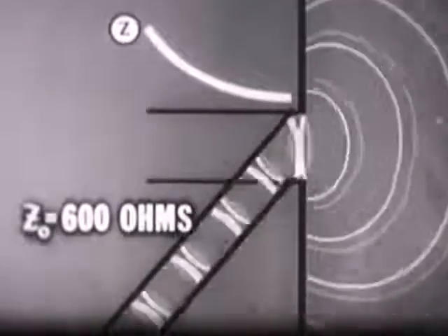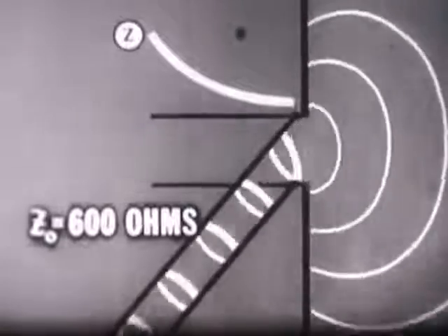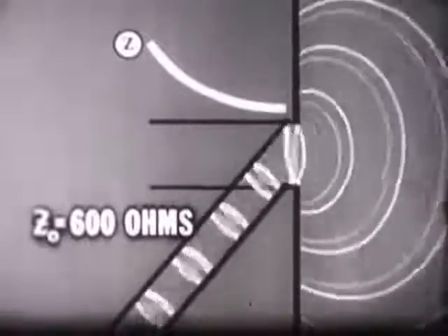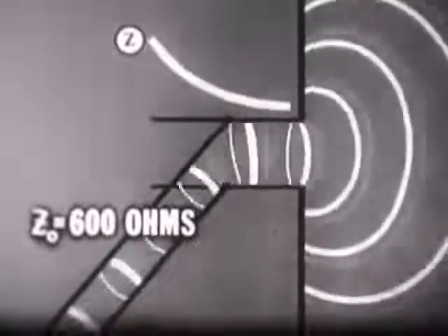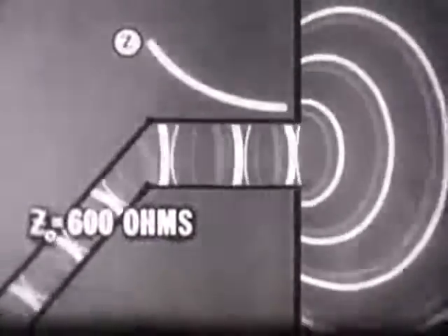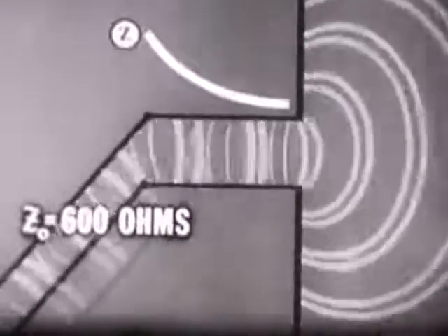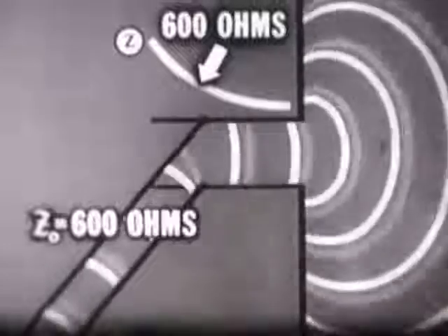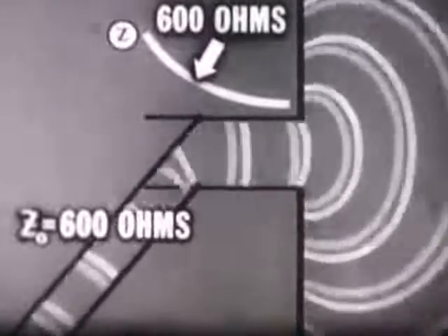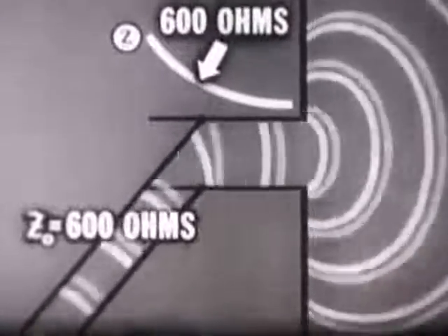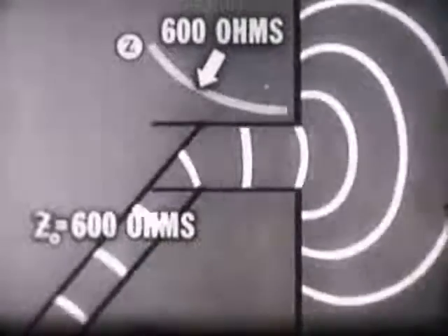This hookup gives us some reflection, meaning a mismatch of impedance values and a consequent loss of power. So, we'll slide our line along the stub until we find the point of matching impedance. The radiation of the antenna can be checked. When maximum radiation occurs, the position of matching impedance has been found.